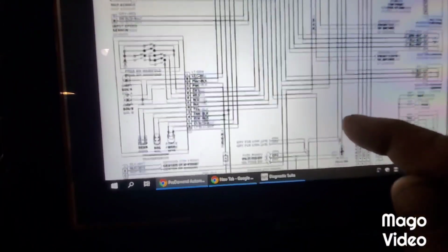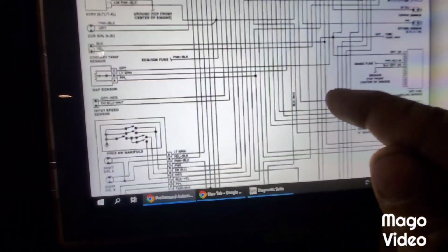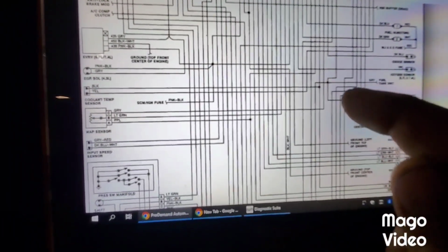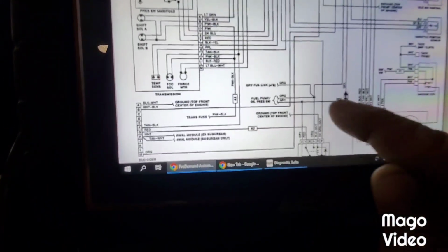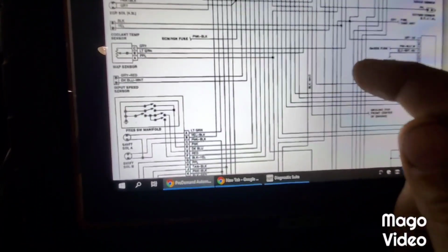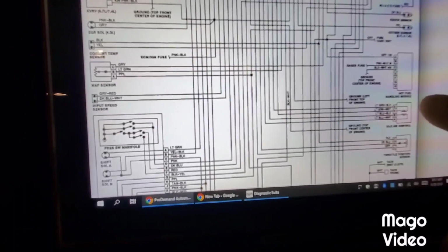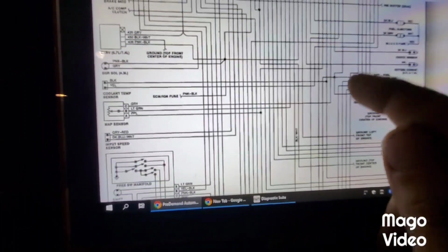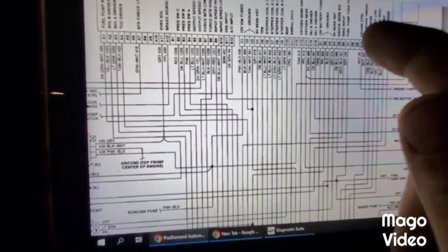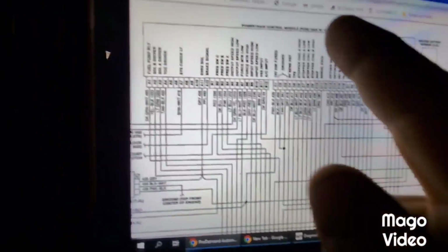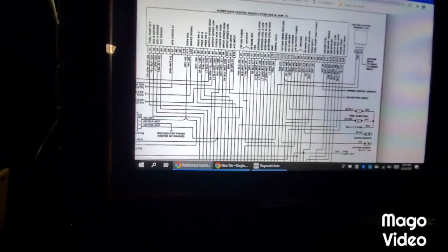Now, I remember this on older Chevys. If I follow that up, fuel pump tank unit, the gray. Chevy seems to always use gray. And it comes to a splice there, fuel handling module, and fuel pump feed fused. So the feed is coming from the ECM.